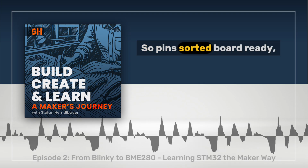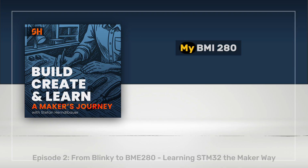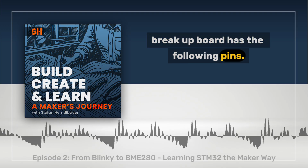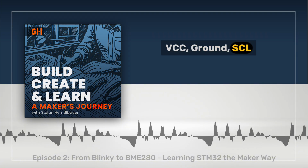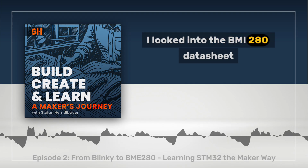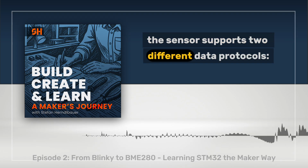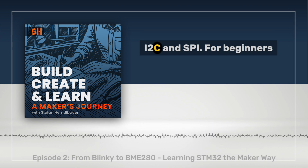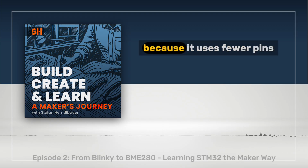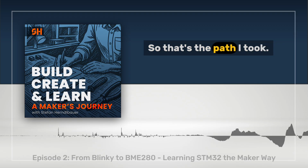So, pins soldered, board ready. Next big question, how to connect them properly. My BME280 environmental sensor breakout board has the following pins: VCC, ground, SCL, SDA, CSB and SDO. I looked into the BME280 datasheet and the first thing I learned was that the sensor supports 2 different data protocols, I2C and SPI. For beginners, I2C is generally recommended because it uses fewer pins and it's often simpler to get started with. So that's the path I took.